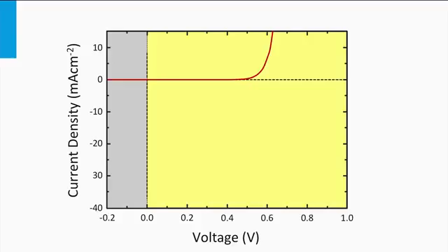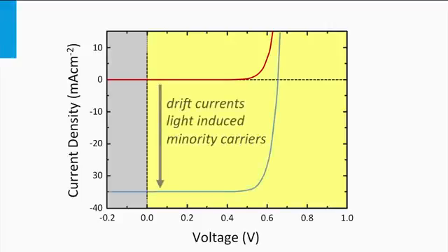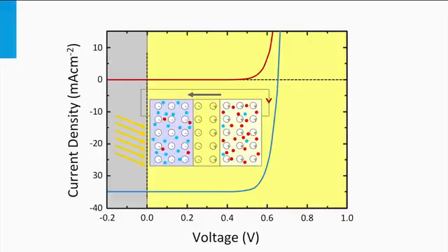Now we look at the IV curve again. The red line corresponds to the IV curve of the diode in the dark. Adding the photocurrent, the typical IV curve of the diode shifts down the vertical axis in the direction of negative currents, in reference to the forward bias direction of the diode. This circuit is the circuit for an ideal solar cell. This means that we have not included all types of electrical and optical losses. We will come back to that later this week.